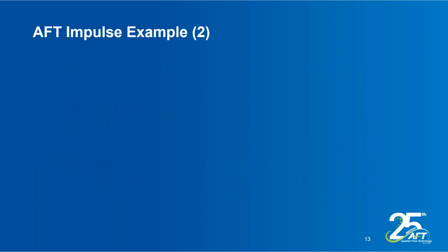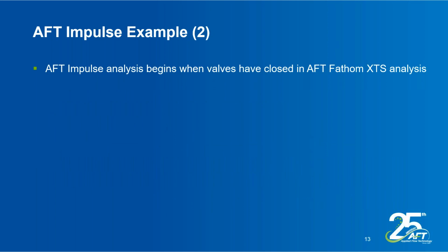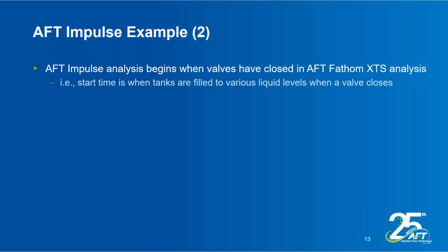So once your model is imported, you just need to set up the transients. Here's where you would be able to use Fathom XTS and Impulse together. And this will clear up where the XTS simulation stops and where the Impulse simulation would start. The Impulse analysis begins when my valves have closed.